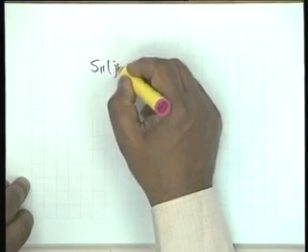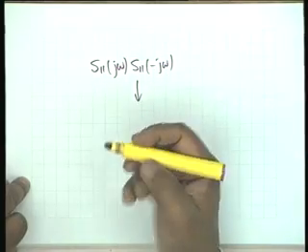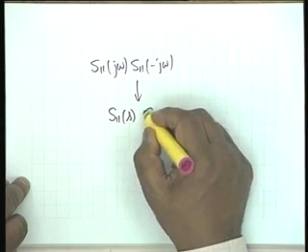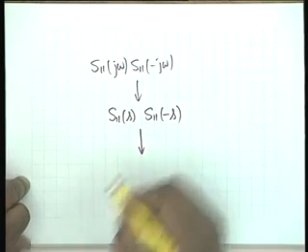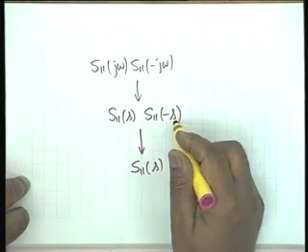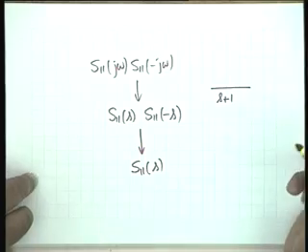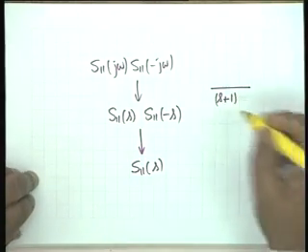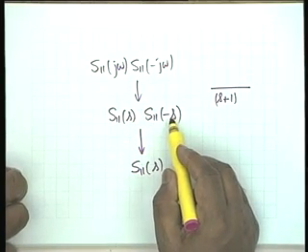Capital S11 of j omega is an analytic function S11 of S, and therefore, from S11 of j omega and S11 of minus j omega, we substitute j omega equal to S, and we get S11 of S and S11 of minus S. Okay. And the next task then is to choose an S11 of S. It is given as a product. Suppose S11 of S has a factor S plus 1 in the denominator, then it must also have a factor... You see, it is a product of S11 of S and S11 of minus S.